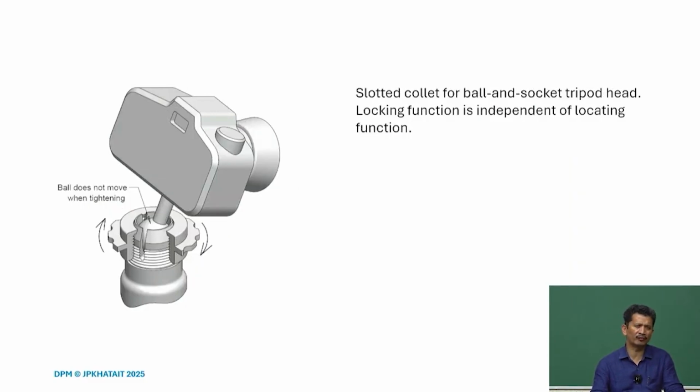One way to address this is a very clever design here. We use a ball and socket head, and then we use a slotted collet. Here we can see the slot, and we are using a little bit of compliance.